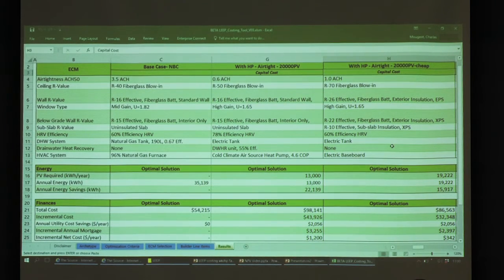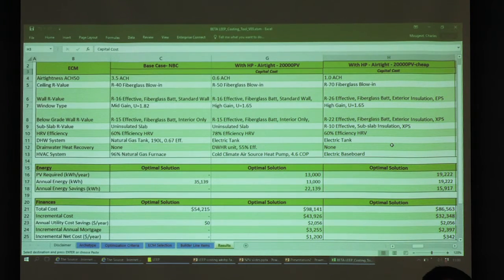Right now, you can't model a high-rise building in HOT 2000, but you can do a MURB unit in HOT 2000. You have to make sure at first that the application in HOT 2000 is correct. It's not going to work if you're trying to model a commercial building in HOT 2000, as your underlying assumptions will all be wrong. But if the housing type that you are thinking of can be accurately represented in HOT 2000, then it can be run through HTAP, and this costing tool could be used to filter the solutions, absolutely.